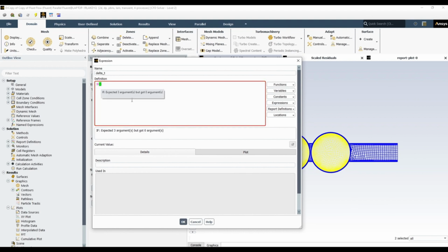For if, use small brackets, and then we want to define the simulation time. When you press t, you can see this is an internal variable, so the expression recognizes t and uses it as the simulation time. So you can use t less than 3. Always write units along with your quantity, so we want to use 3 seconds.